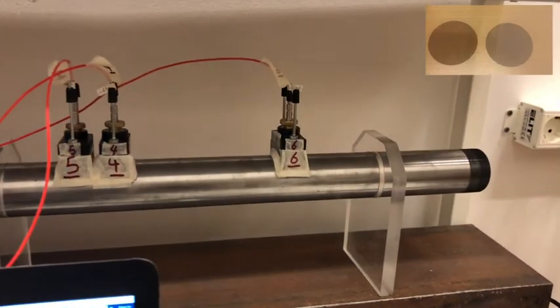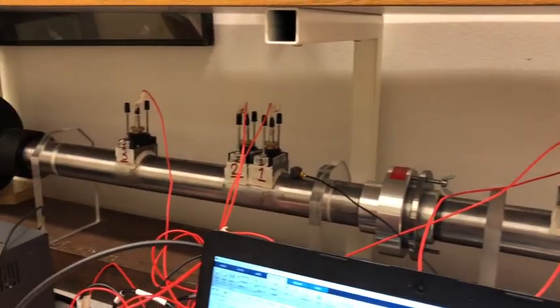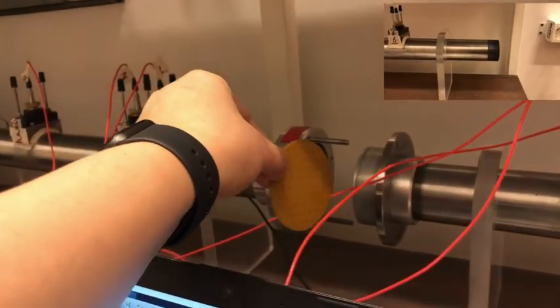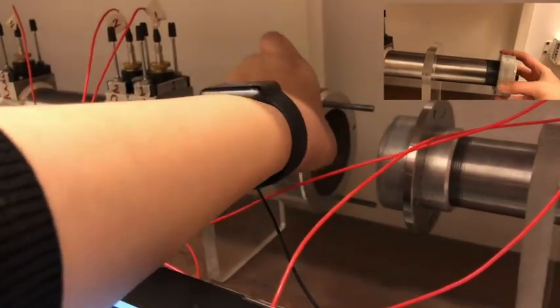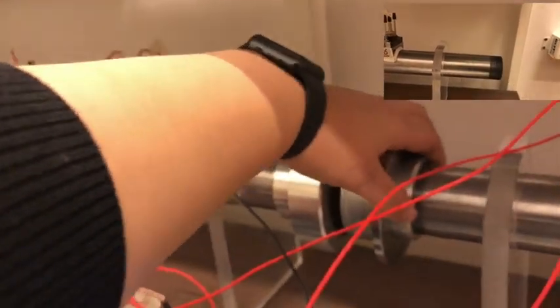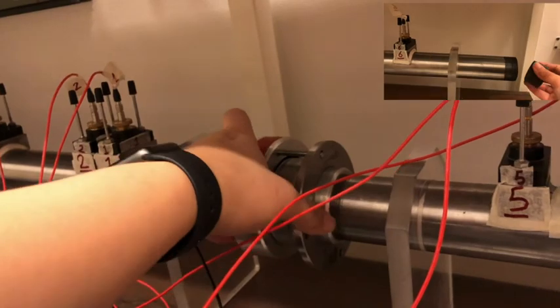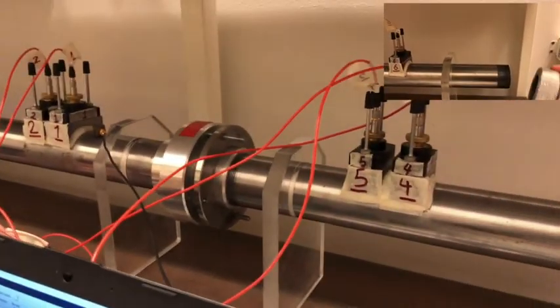This is my actual setup and these are my sample. I put the sample in the middle of the duct, and with 3 ending conditions, I capture pressure and velocity at the sample. And then with the help of model, my scattering matrix, I study reflection factor, transmission coefficient, and absorption of the sample. To what I said, there is more to know and there is more to explore. And we hope we can come up with a good solution for that.